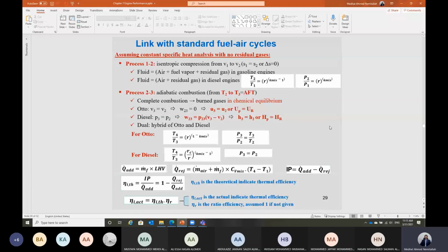The performance curve should give us the brake power and the brake specific fuel consumption as a function of the engine RPM. And then we can plot this map. Getting this map, we can store it on the engine electronic control unit, engine ECU. So at a given loading condition, at a given RPM, the engine already knows the amount of fuel that should be injected, and the timing of the exhaust valve, when it should be open in order to have the exhaust gases released. So everything should have been calculated before running the engine of your car.